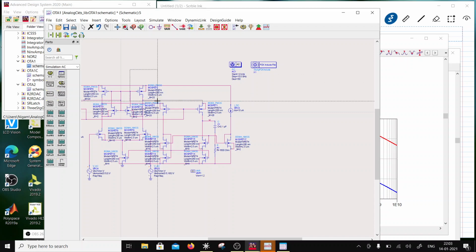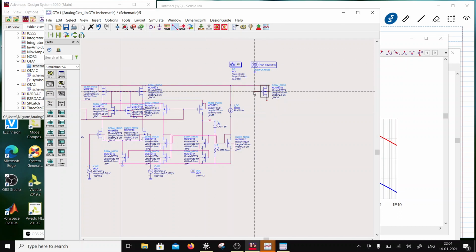So what I will have is one of these transistors repeated as a mirror to mirror this current, correct? So this is going to mirror that current, so this is going to come from this, and then I'm going to repeat the same transistor as a follower. So in this case I'm going to take this and I am going to have a follower here, right?